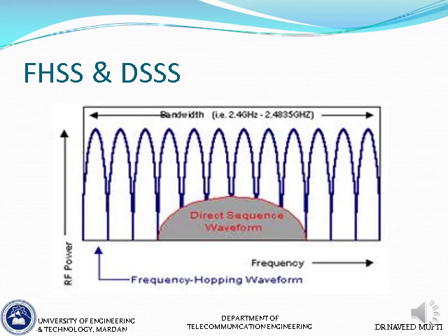Now comparing the two types of CDMA, the frequency hopping spread spectrum and the direct sequence. So the direct sequence, as explained in the last slide, that usually happens within a larger bandwidth of, let's say, 5 megahertz, but it is happening at low power. Whereas in frequency hopping, the carrier bandwidth is small. As you can see, these are all different carriers, but the signal is made to hop between different carrier frequencies within the allowed band.